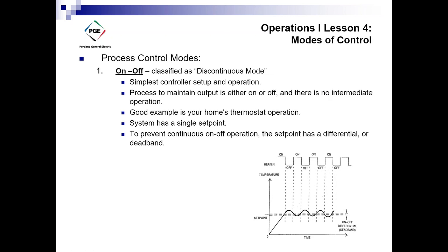So just a picture showing this. I mean, this is a reference to our time and the set point, and so this is the error signal. It's either on or off. And so this may represent the deadband. So you may have a set point of 70 degrees, an upper deadband of 71, and a lower of 69.